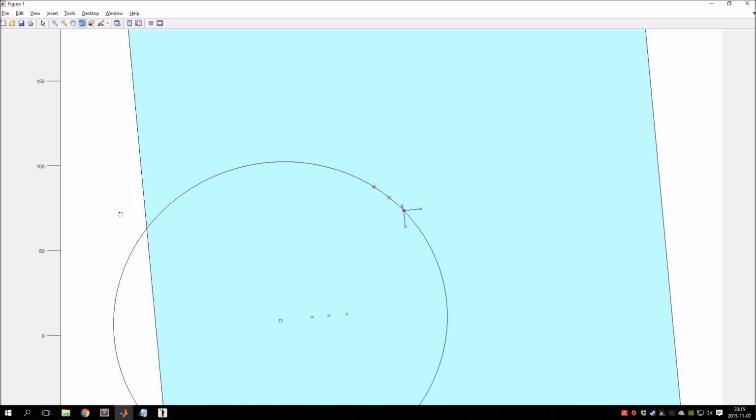Obviously, when you have this kind of radius from the circle, you can get better approximations of where the target is or where you should beam. So if I beam right here on this side of the target and I know how large this circle is, I can take a larger step and end up on this side, and what I get returned is a position on this side of the circle instead, and that way you get a bit more accurate estimation of the circle radius and circle center point here, so you get a bit more accurate position of the target.